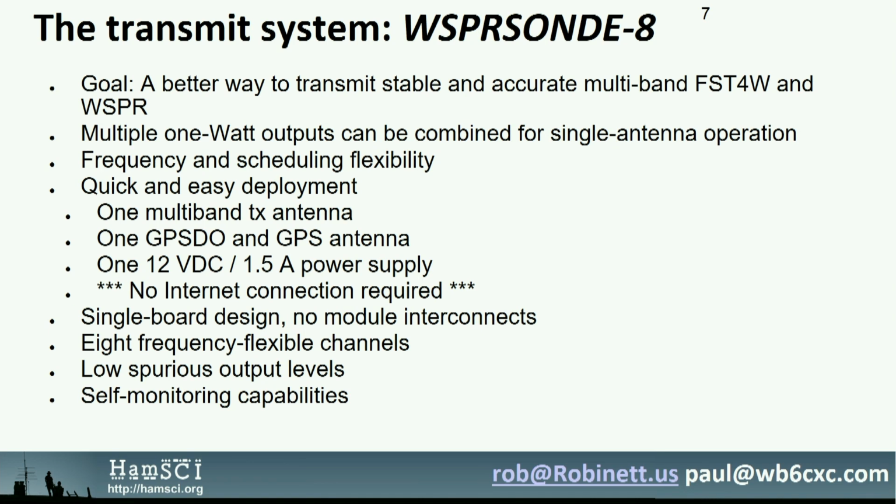Thank you. So the WSPR Sound is in its second generation. For the October eclipse, we deployed a 6-channel version, but it's using what is now fairly standard technology: Si5351 synthesizer chips, which just about every modern radio has, and a little bit of software to control the frequencies and the modulation.